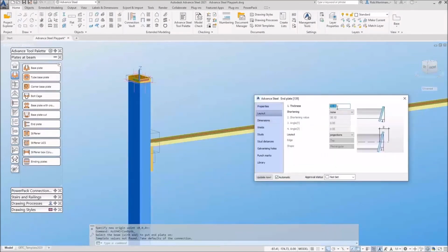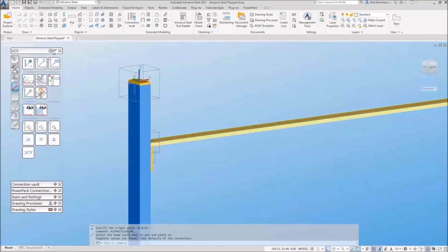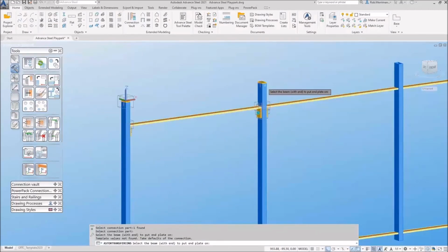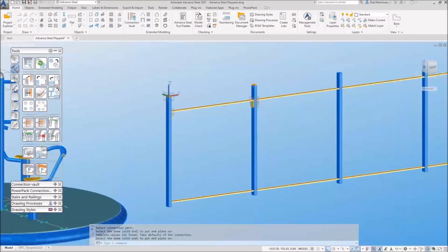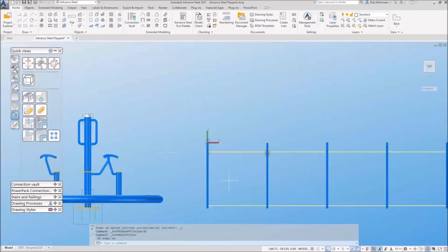And again, we'll make that 5mm thick. We'll shorten the post by the plate thickness. And we'll just say it's a 6mm fillet weld all around. And then we'll joint copy that to the top of that post. So the one I was going to look at is the sort of looped bars.